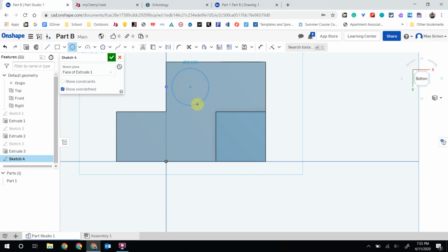So we're going to draw that circle out here. So we know this one's already there in the middle. So we need to use our dimension tool anyway to take this and lock that in at 12. And then we need the smart dimension. We've already told it to lock to the center here, right? It's 7.5 because 7.5 is half of 15, which is this depth here.